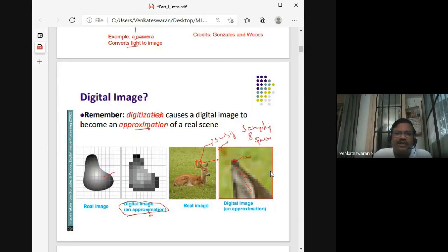Sampling is exactly here: we take samples, because it's all about what is happening in this portion of the image, and that is getting reflected onto this. So can you reduce the size of this block so small? If you can go down to a very small size, then you are actually sampling at a very high rate, which is called spatial sampling.